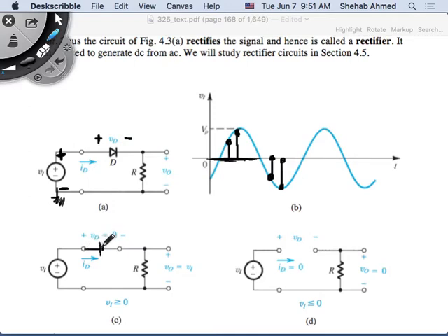It will be a voltage that opposes the current to flow, right? So only when the input voltage becomes higher than 0.7, isn't that what we said? Only when the input voltage becomes higher than 0.7, so this minus this should be higher than 0.7 for the diode to start conducting, right? We will look at this later, but since we talked about it, I might.